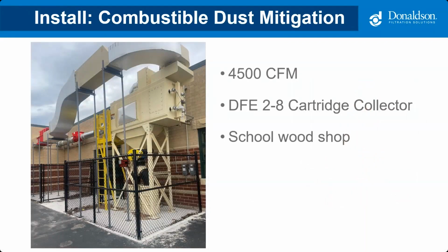This is a recent job I did, another wood shop in Wisconsin. This project was in Dodgeland in Juneau, Wisconsin, a filter cartridge unit handling 5,000 CFM. As you can see, the dust was combustible, as I talked about before, and as part of the mitigation strategies, they went with inlet and outlet isolation and explosion and dust discharge isolation, all shown in this picture.